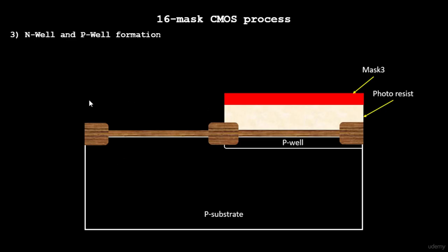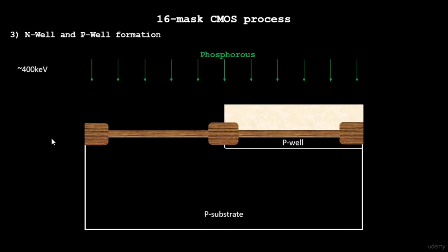If you see over here how the silicon nitride has protected the areas underneath, while it was not able to protect the areas at the edges because the growth is so strong. But it has clearly protected the maximum area, almost 90 to 95% of the region underneath, from the silicon dioxide growth, while the silicon dioxide has been grown in this area and this area.